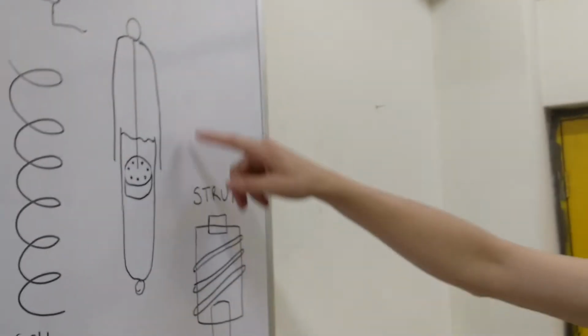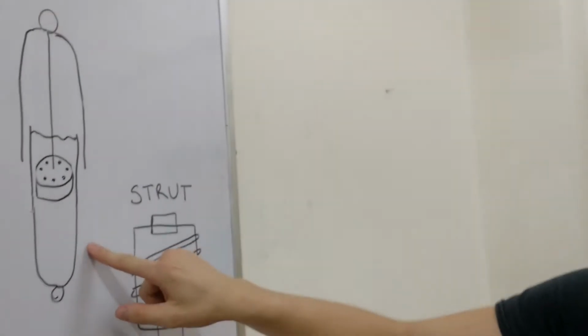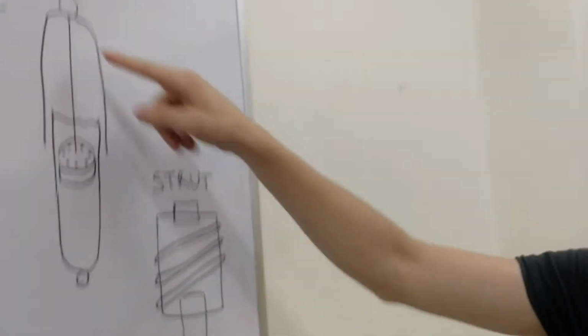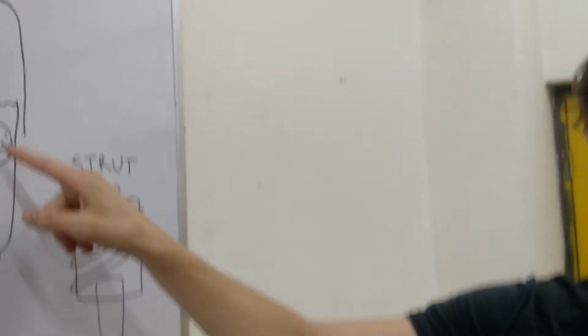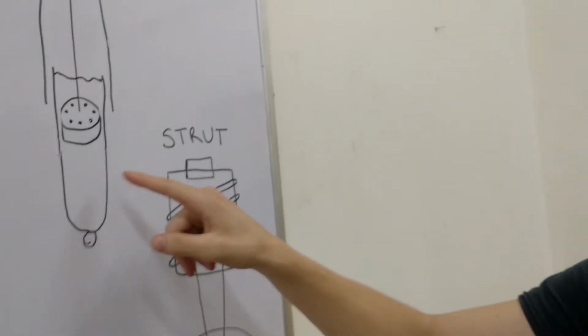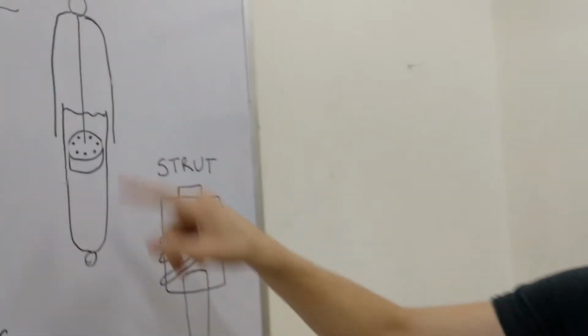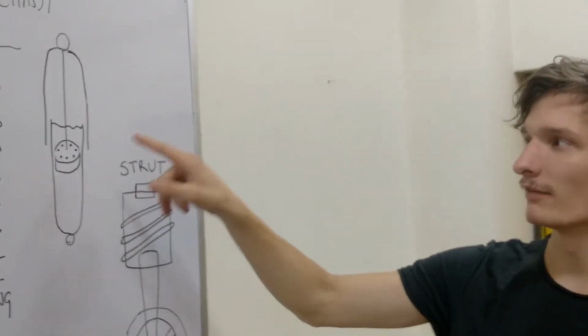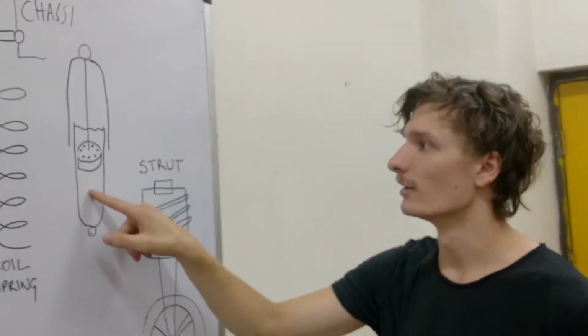Let's go. Okay, the damper in a car is built like this. You got two tubes, one outer one inner one. In it you got a piston. In the piston you have little holes, and in the lower inner shell housing you have hydraulic fluid.